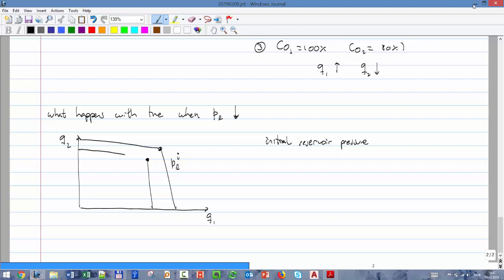So this is for reservoir pressure 1, and this will be for reservoir pressure 2, and so forth, where reservoir pressure I is greater than reservoir pressure 1, which is greater than reservoir pressure 2. If your combination of points is here, it is going to be perfectly fine for all of these reservoir pressures, but there will come a point where it becomes unfeasible. The area will shrink so much that they will become unfeasible.